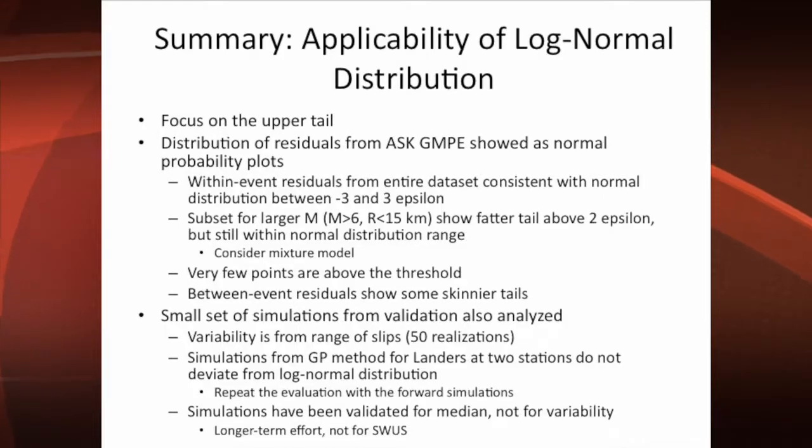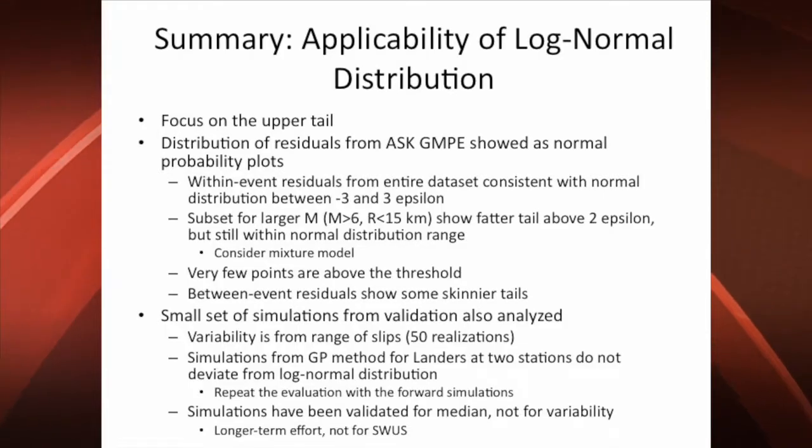Yeah, pinning it down is difficult, so there will still be high uncertainty in what this part of the distribution looks like. Fortunately, it's showing up beyond 2 epsilons, right, and really beyond 3 in most of these cases, in some of the cases. So now that part is not driving our hazard in the 10 to the minus 4, 10 to the minus 5 range. There our epsilons of 1 to 2 typically are going to control that number. When we're going to the higher parts, 10 to the minus 6, 10 to the minus 7, then these will be an important contributor to that.